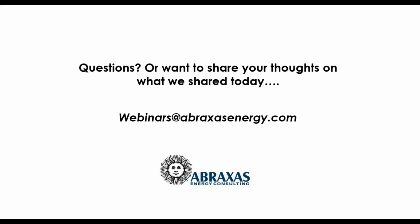Universal Translator does a slightly different version of that, where the temperature dependence, instead of heating degree days or cooling degree days, they split up the temperature for some reason into like 5 or 6 pieces, and so they figure where these breakpoints might be, and then they say this is the dependence when we're below 30, and this is the dependence when we're between 30 and 45, and then on top of that add in the hour of the week parameter.